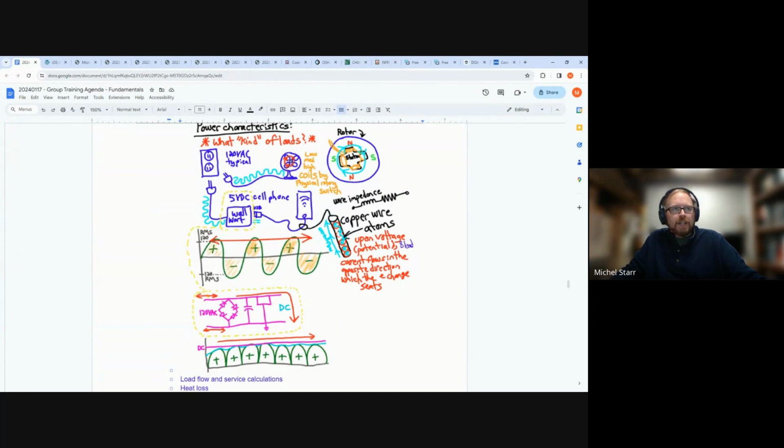To change speeds of motors, like for a typical household fan, there are multiple coils in there. You're physically going to a higher or lower voltage, and that's why it spins faster or slower. Commercially or otherwise, in the HVAC and the motors that we use in buildings, other than in residential, usually they might have a contact starter or a combination starter. So we're saying plates coming together to turn off and on.